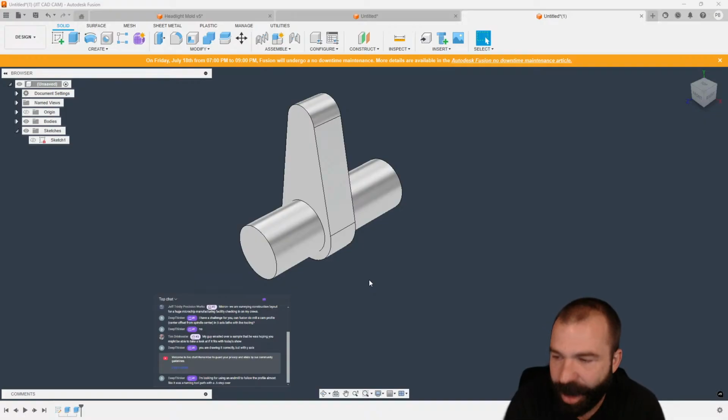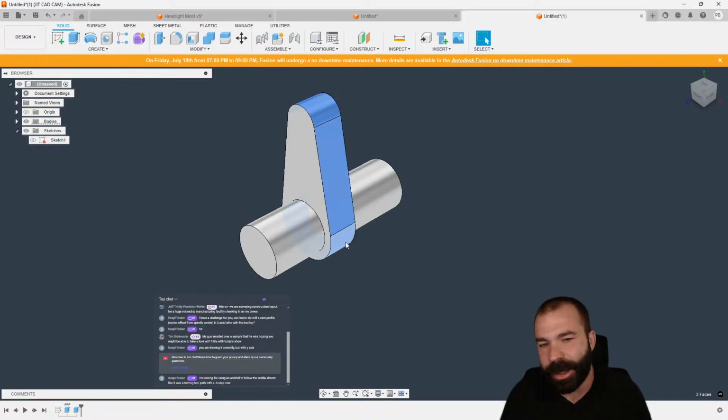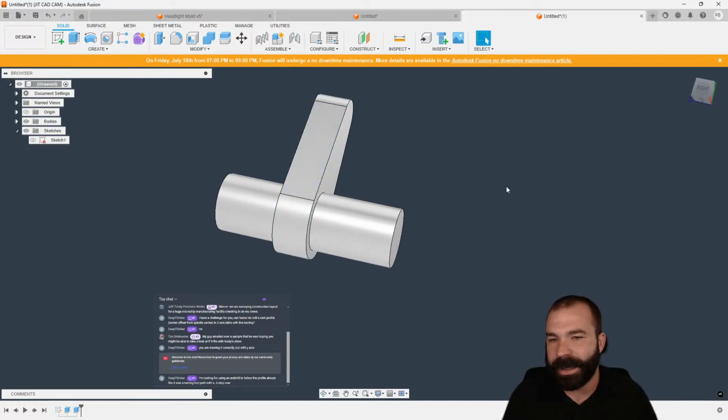I think I know. Okay, so Deep Thinker, presumably I initially thought you wanted to use a ball end mill to go around the outside, right? Coming in on the X. But what you're saying is you actually want an end mill to come in on Z, right? And machine with the shoulder of the end mill around the cam lobe, right?